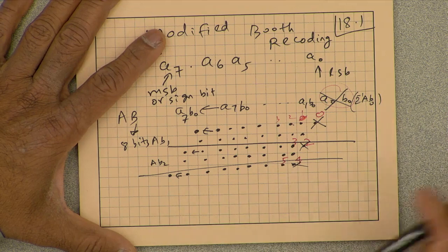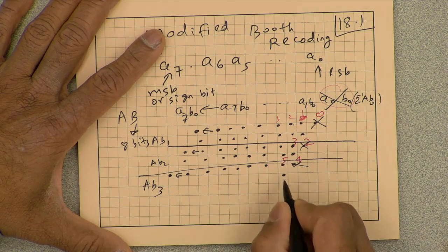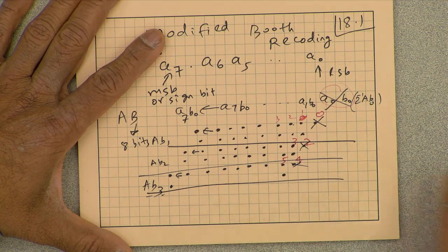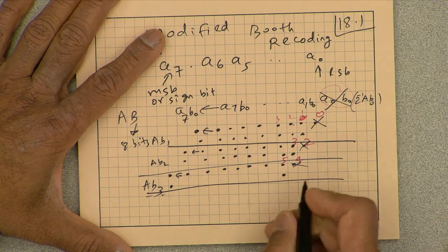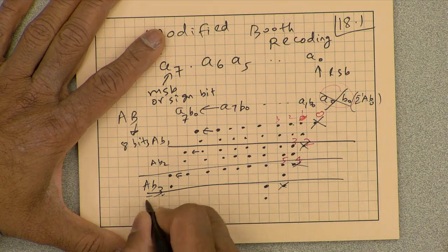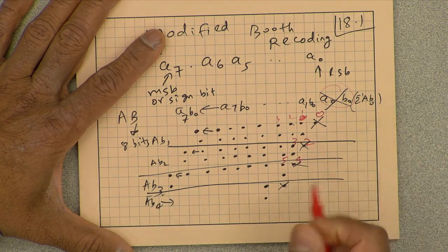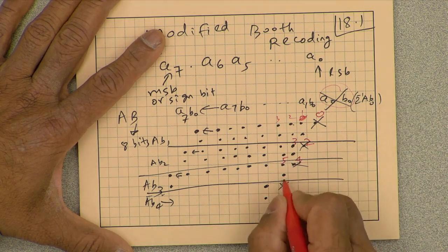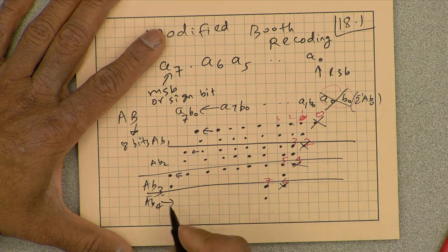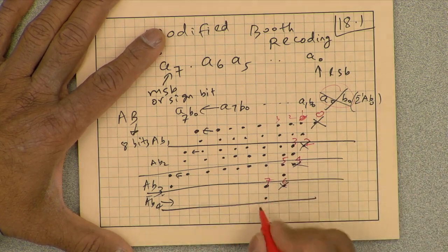So then AB3 can begin at 5, and again we throw that away, and AB4, which is here, can begin. So this is 5, that's 6, that's 7, so AB4 can begin at clock cycle 7. I'm not going to write a lot more.